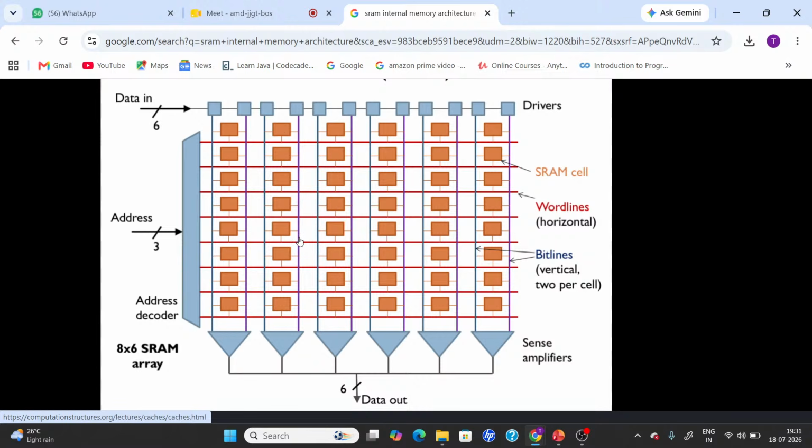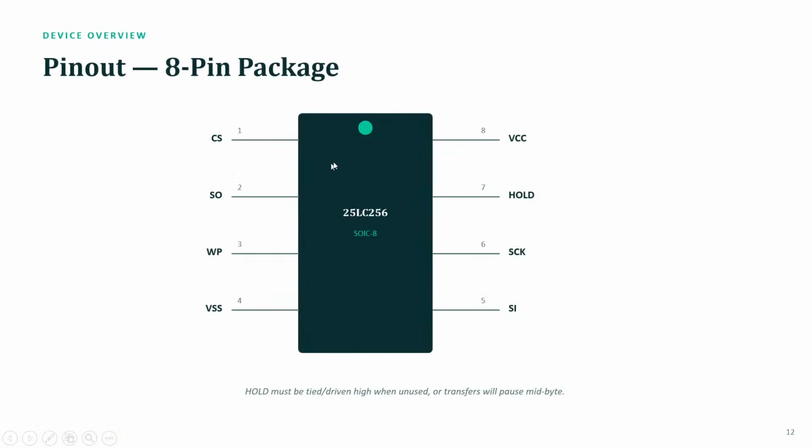When you are sending data to your EEPROM chip, this chip also has some kind of internal memory architecture. Whatever data you send is not directly stored inside your byte. It has something known as a page buffer, where it stores the data. After the user has sent all the data, it forwards the data from the page buffer to the internal memory architecture.